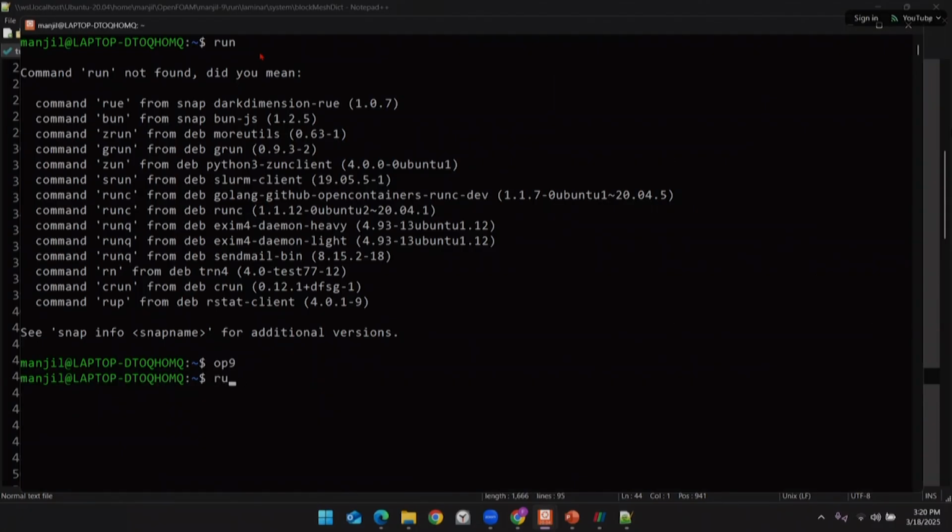After this, type run, and you'll be directed to the run directory. Inside the run directory, you have your laminar case, right? So type cd laminar. This tells you to go inside the laminar case. In this way, you can direct yourself to the laminar folder. Did you get it? No, it's showing no such file or directory.